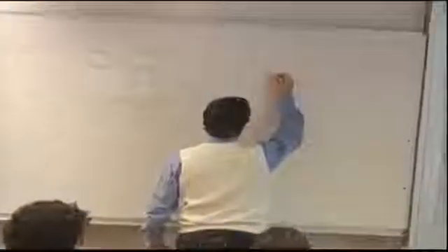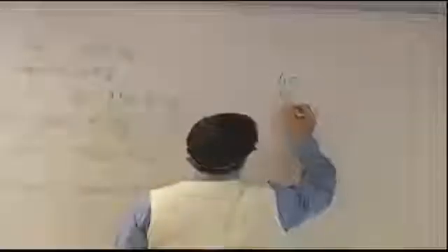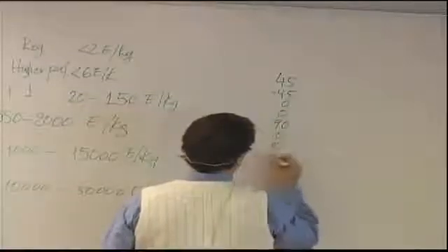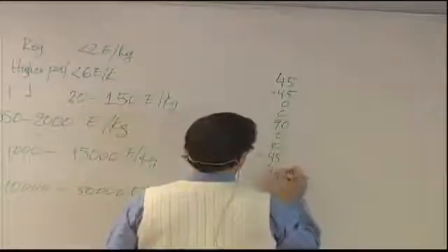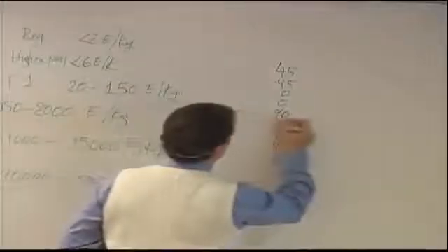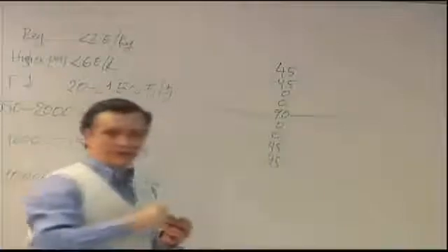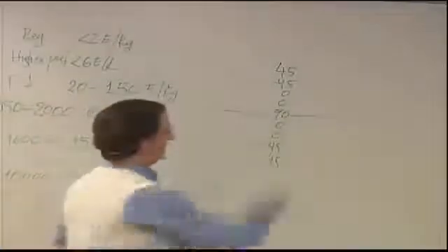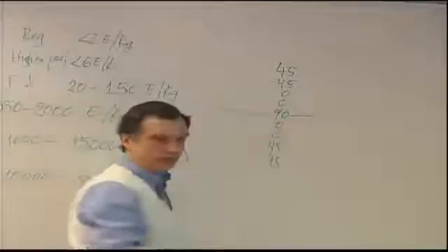If I were to write it, this is the full stacking sequence. So the mid-plane is here, and that's what the overbar means. The overbar means I only have one 90, because if I didn't have the overbar, it would mean that I have two 90s next to each other and the mid-plane is in between the two of them. That's just for reference as far as this course is concerned.